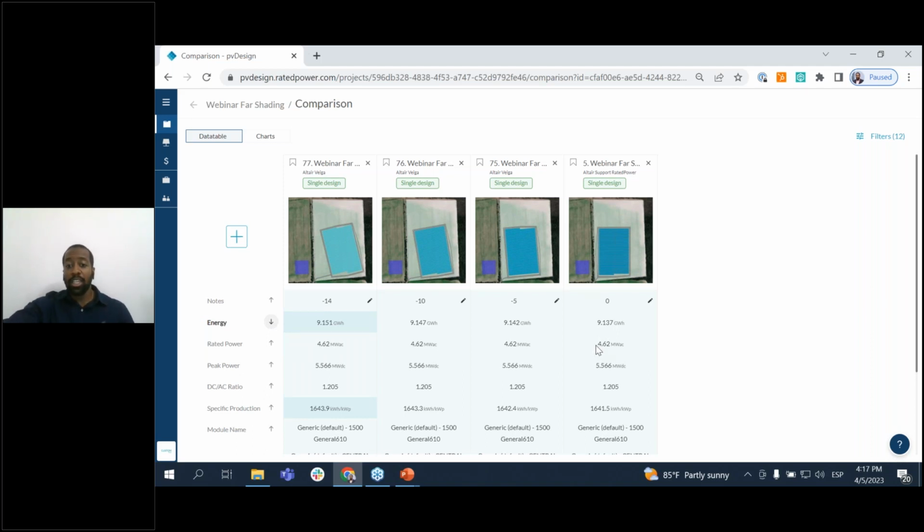And as we can see here, as I change my azimuth towards the north and the west side, my energy yield is also increasing, okay? So the ideal case is that we would continue to run different iterations, changing that azimuth until we reach that peak level, right? Where we'll be getting the highest energy production. And then from there, we can proceed to other things. Of course, if you keep rotating that, there will be a point that the production will start going down. So you just need to find that peak value, and you should be good to go.